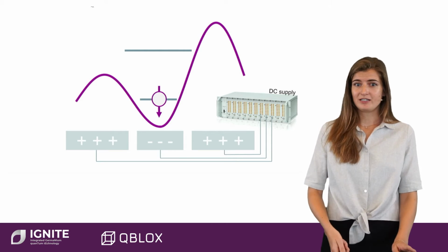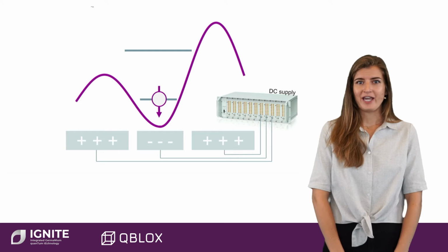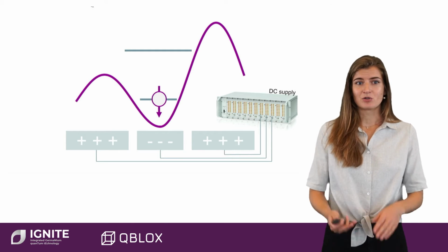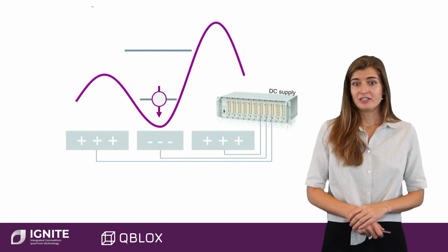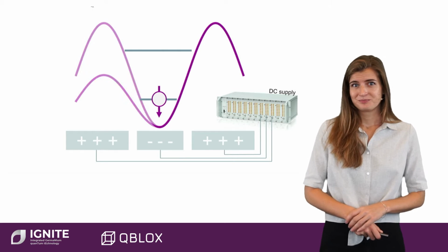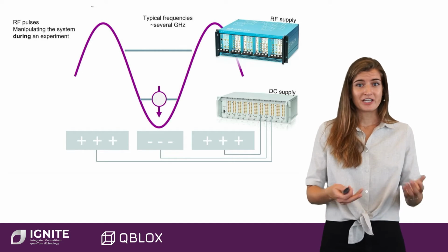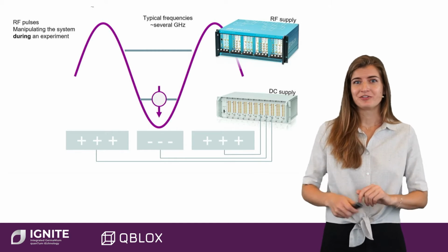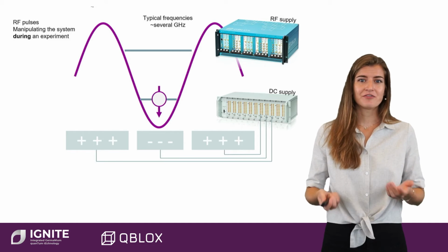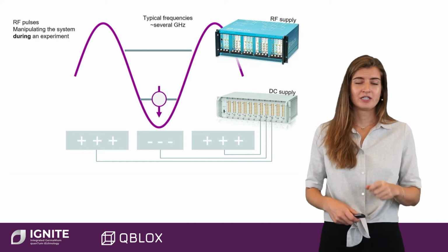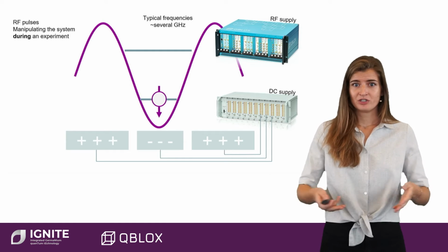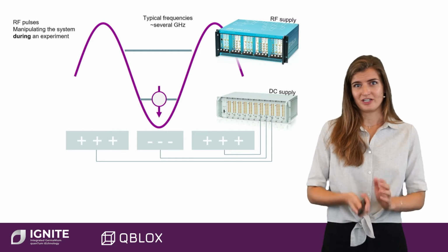Manipulation of the spin state can now be accomplished through adding energy to the system at the according frequency, defined by the Zeeman splitting, within the decoherence time of the qubit, bringing us to the need for pulsed high-frequency signals. The RF frequency is required to be addressable within the line width of the qubit, and an entire pulse sequence should take well within the coherence time of the qubit.